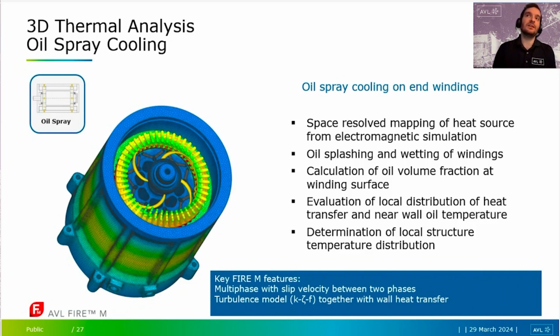So with that, you would want to understand your oil volume fraction on the winding surface. How wet are the windings? What's your heat transfer distribution on the windings and near the wall? And then effectively your structure temperature is the macro KPI for this.